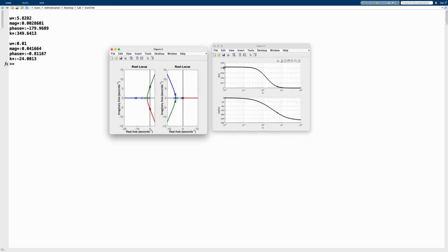Ideally, what we want to have here is that this line should be at equal to 1, so gain 1, so that we are basically outputting our input. And then at some high frequencies, we should have 0 to reject basically high frequency signals, which is probably noise. Because references will not have high frequency components whatsoever. Of course, they will have maybe some of them, but the whole signal will not be a high frequency signal. Therefore, we want to have low frequency tracking, high frequency rejection, since we know that noise is high frequency.